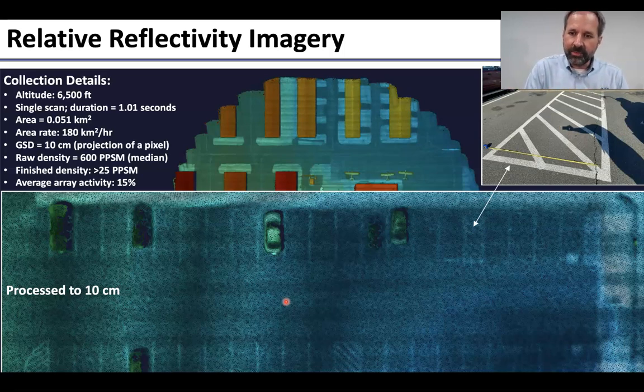So that means on that curb, we're now at a different point. And what we see is more speckly patterns. There's more voids, places where we just didn't have enough photons within that smaller box size to declare the presence of a surface. But where we do have enough signal, like these lines and that sort of thing, you get better spatial resolution. The voids on some of these cars, like over here, are kind of indicative of finishes that maybe are highly reflective or highly absorptive.